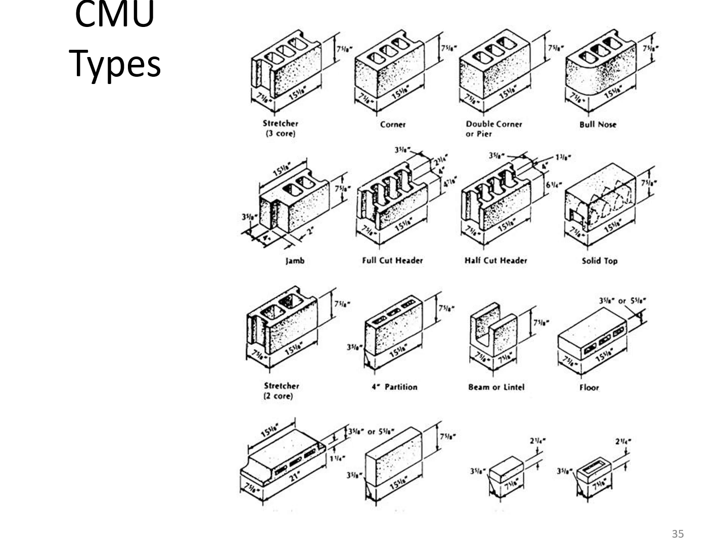So here are some of your CMU types, the different profiles. You see the top row. Sometimes you have the end blocks there, the two in the middle. The one on the far left is for working along through the middle of the wall. You have the rounded edge, which is another idea if you're using that at the corners of the building. Then you have other different types of ideas for interlocking type bricks. You see the U-type that I said down in the third row, third one over. That's for laying the bars, rebar, inside, and a few other different odd profiles.